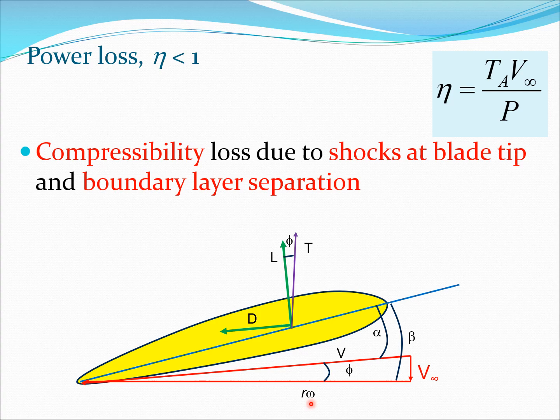Now, we have discussed all these issues related to compressibility before, so this does play an important role, and this is something which limits the propeller speed. So, for example, most propeller aircraft only fly at lower speed regimes because even while V infinity is relatively low, the Mach number is approaching compressibility, or near 1, in many situations. So you may encounter transonic flow problems even though your V infinity is maybe in the high subsonic region and so on.